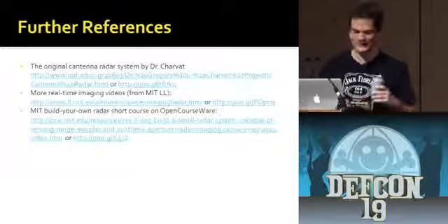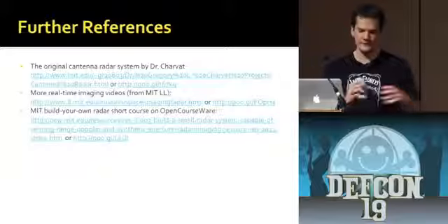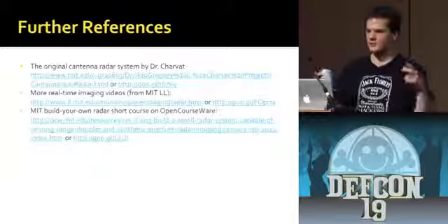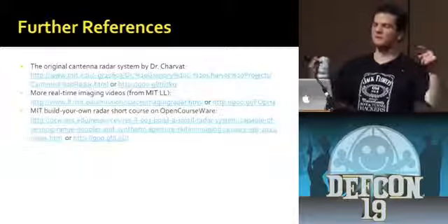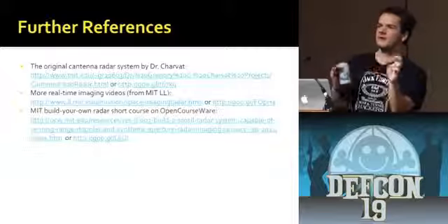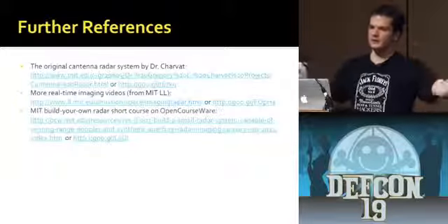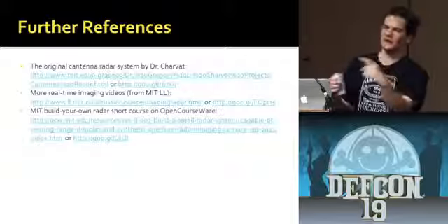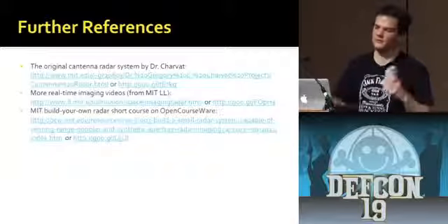But yeah, it's pretty open. You basically get different characteristics. If you're trying to do the SAR imaging, having a wide beam width is actually somewhat useful. It decreases some of your spatial fidelity, but you also get a wider image. If you have a very narrow beam, you're not going to get any signal from something that's further apart. So it's a trade-off there.